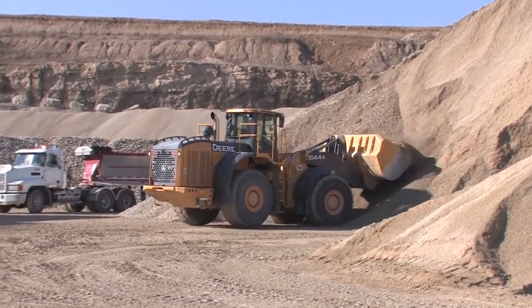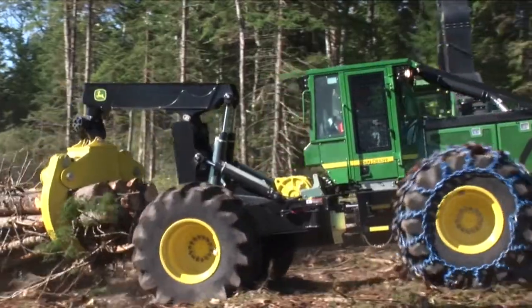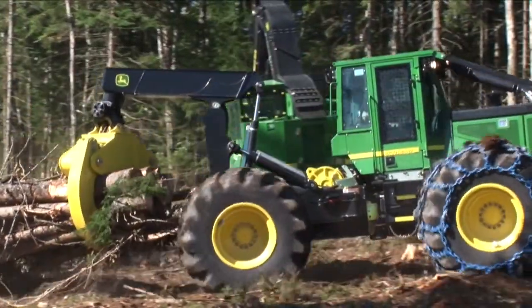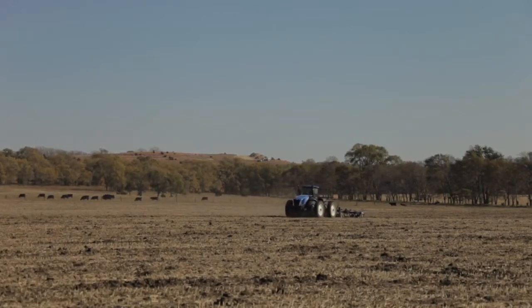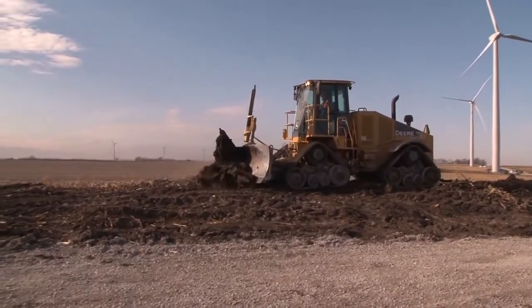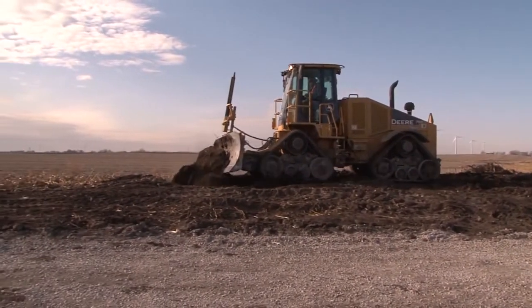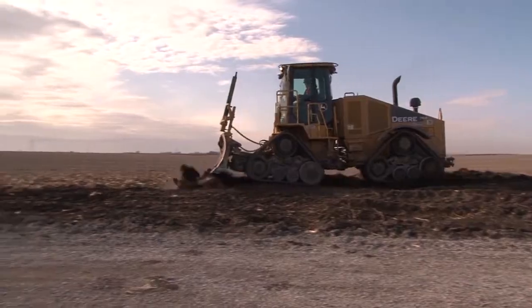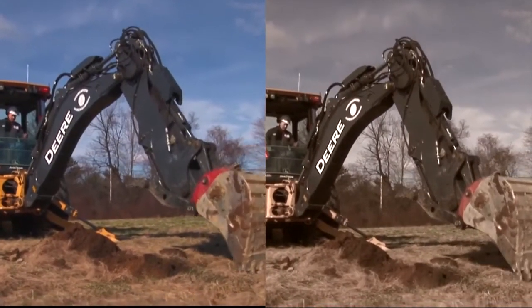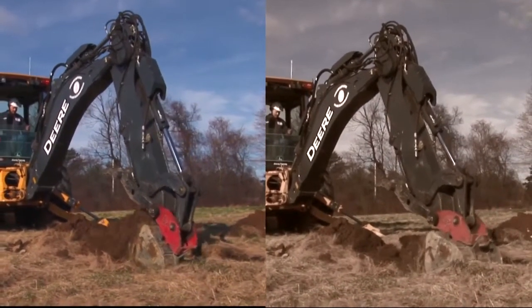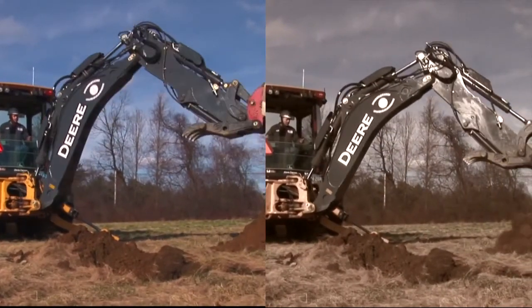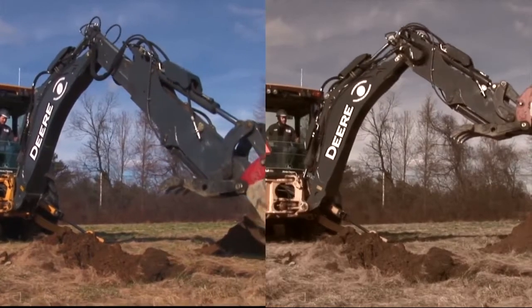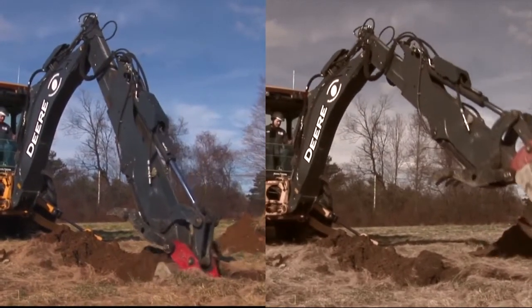Even before a breakdown, contaminants in fluid can reduce system efficiency. This is as true for fuel and engine oil as it is for hydraulic oil. A less efficient system is a less productive system. These productivity losses can go undetected because efficiency loss is gradual. In hydraulic systems, for example, efficiency can drop as much as 20% before the operator detects a change in operation. That's losing a day of productivity each week.